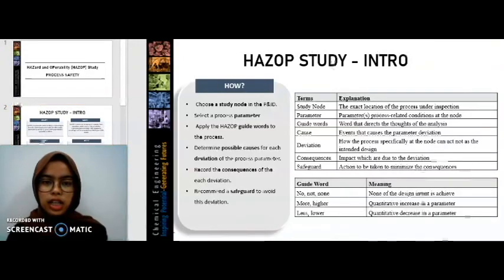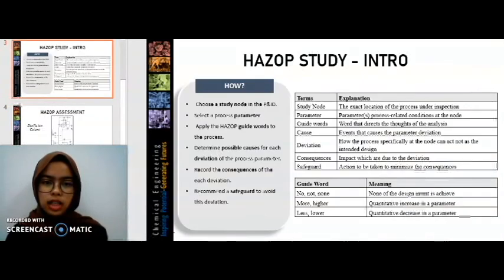How is HAZOP actually conducted? A HAZOP study uses guide words to systematically determine possible failures that could result from operation of equipment outside of design conditions. This can occur due to possible maloperation or malfunction of individual items of the equipment. Then a list of necessary actions and recommendations to improve safety and mitigate consequences of hazards will be prepared in the form of a hazard report.